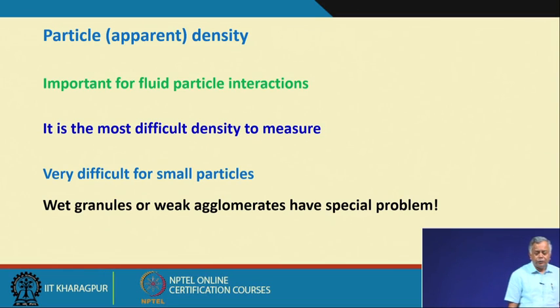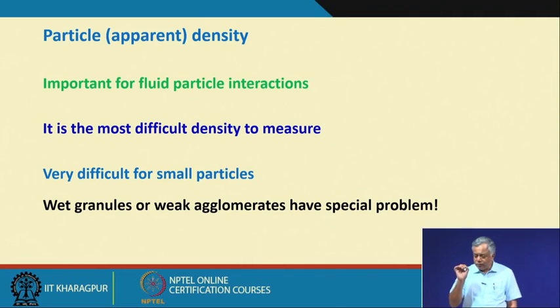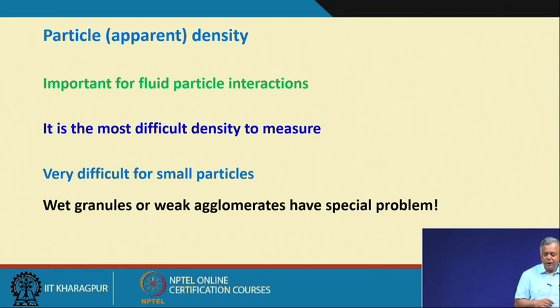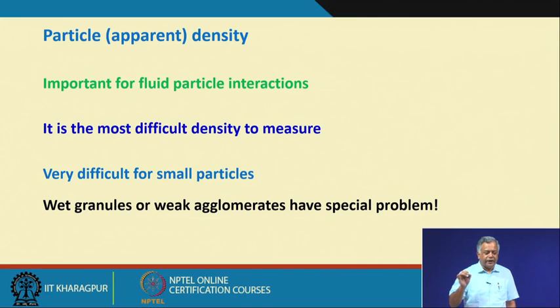you have to ensure that the inherent pores of that particle should not be occupied by a fluid other than whatever gas or air it has already, because when I am dropping it into water, the water may get inside that particle through the pores and can displace the air, and I can have a different density than what it exactly is.